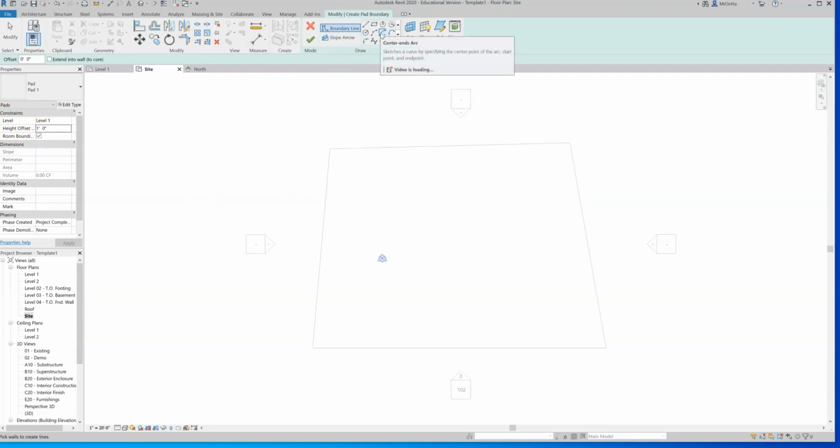Now, in this little window, we have the ability to draw different shapes. You've got to go and scroll up. I don't know why you have to scroll up, but you do. And there's the line or rectangle tool. If your house is a perfect rectangle, you might consider just doing the rectangle. But most likely your house is made up of kind of like that cookie cutter shape we talked about. It probably has some bumps in the foundation. So click on the line tool, and somewhere in the middle of your lot, you can start to draw your foundation. So this is the border of your home, the outer walls of your home, right? So start in one of the corners.